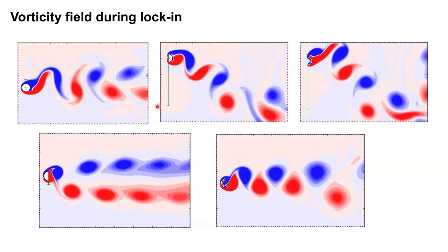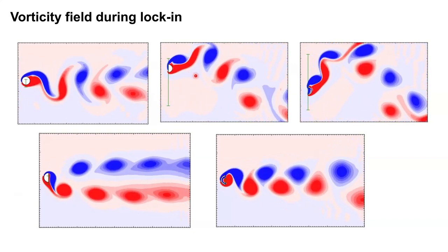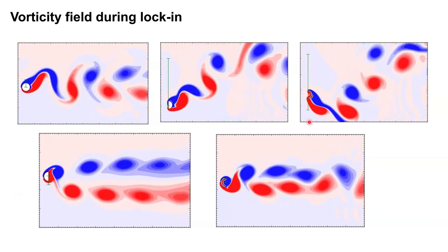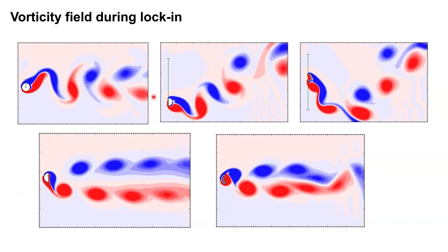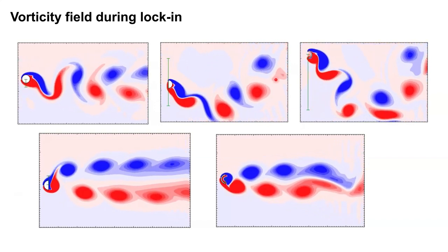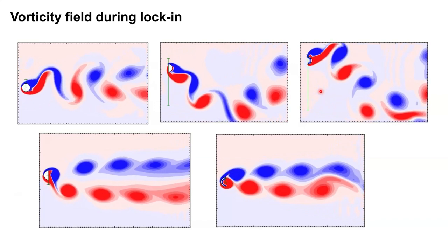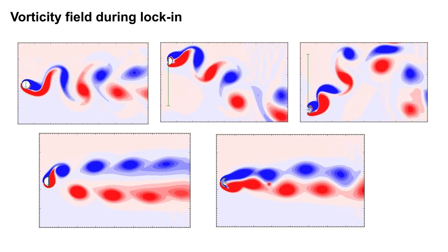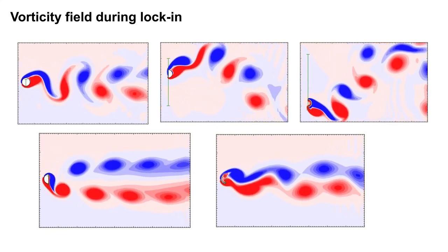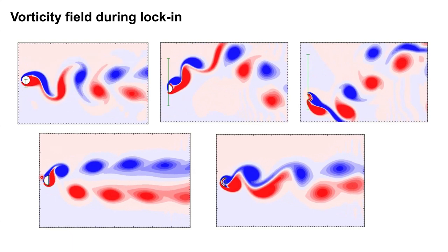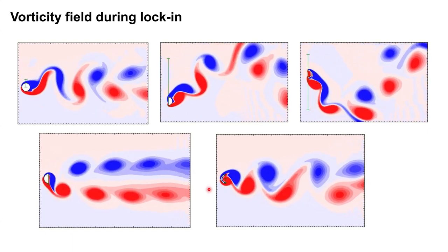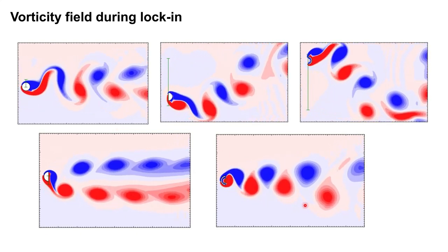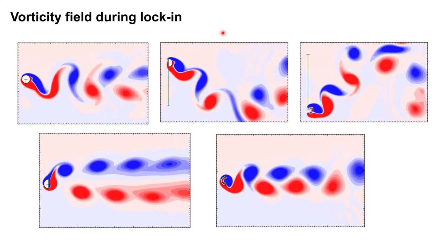Now you see something special in D, as we have seen just before, and also in inverted C. You can see they are moving much wider, right? I mean, this arrow is much larger and the vortices are very spread out. And these are clear signatures of galloping, as we discussed. Now, what happens in D and inverted D and C are reduced amplitudes, as you can see here. Especially C is even lower than the circular cylinder. So clearly our after body and front body are affecting our flow induced vibration.